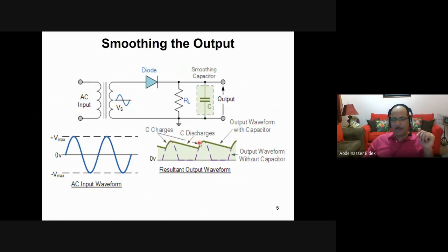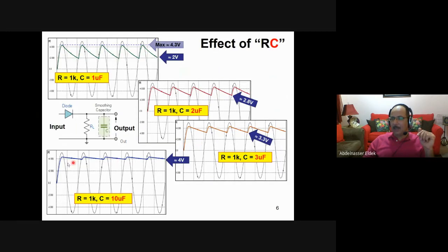Of course, if we have higher resistance and capacitance, then here this is the peak, close to the peak. So as if you are actually curve fitting for these peaks. Imagine that these peaks are different. So here all the peaks are 5 volt, for example. But assume that this is 5, and this is 3, and this is 2, and this is 1, and so on. What happens is that the output will follow the peak. So it will be a peak detector.